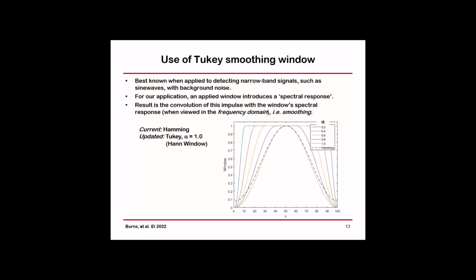The window multiplies the estimated line spread function, and multiplication in one domain is, of course, a smoothing in the frequency domain. And since our objective, the result of this analysis, is in the frequency domain, the spatial frequency response, it applies a smoothing. So we would expect, for the Tukey window, which has a parameter alpha, that for an alpha that is a low number, there is a wider window and therefore less smoothing.